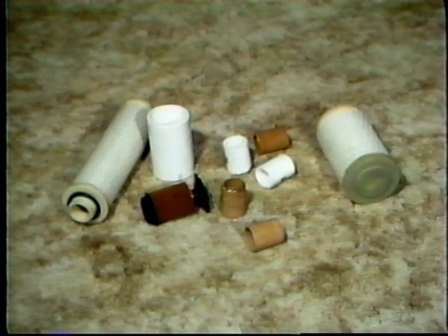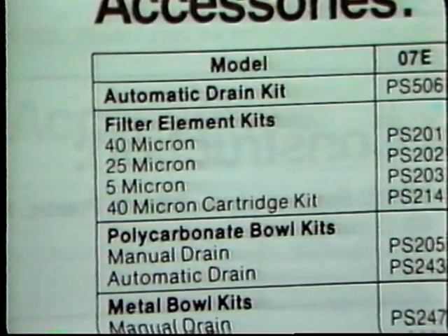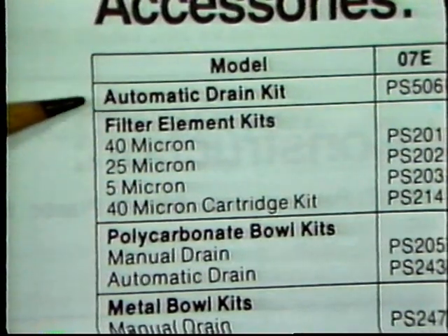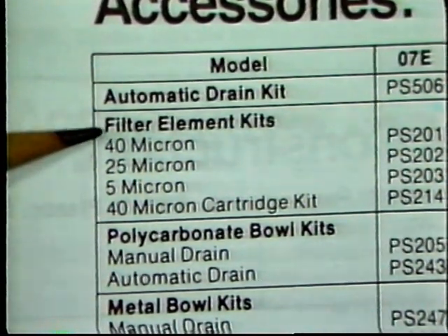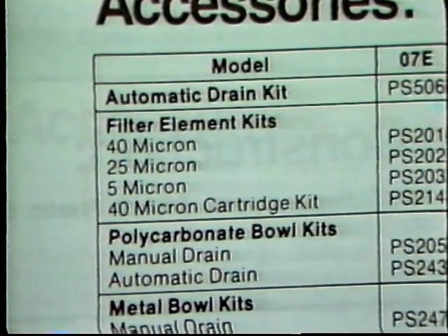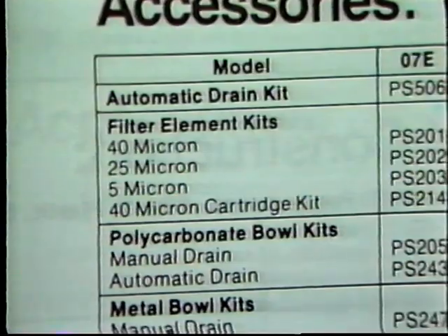Because of its construction, an airline filter may have many pores of different sizes, many of them small, some of them relatively large. If the element has no consistent hole or pore size, a filter is given a nominal rating. The rating is established by the manufacturer and indicates the expected average hole size in the element.